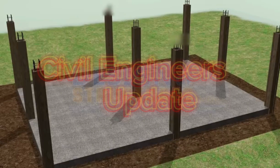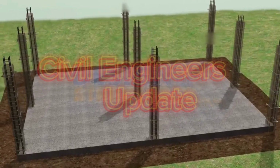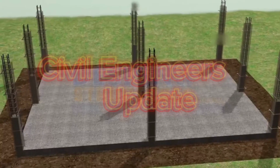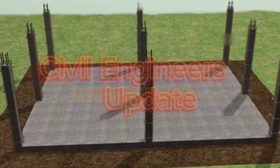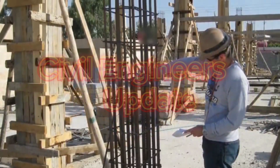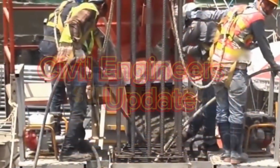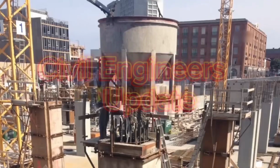Column concreting. After the concreting of the footing is complete, immediately, in a day or two, starters for the column should be cast with proper alignment. Columns are very important members in RCC design. Wrong placing of a column may affect the overall behavior of the structure. Concreting of RCC columns should start from the center of vertical bars and go towards the ends.